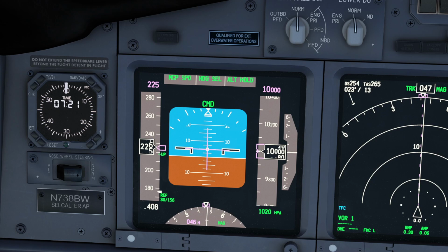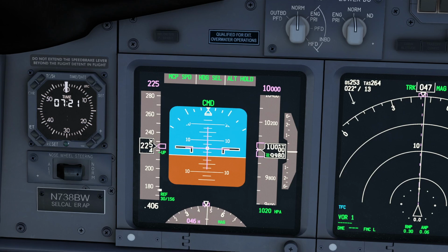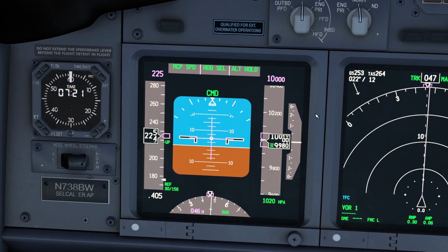The second one is that you must be in a balanced condition. I will use the word balanced because actually the manual says that you must be in trim, okay? So you must be in a trim condition, but like the flight director, it doesn't need to be 100%, but at least you need to be in a balanced position. So pretty much you have to release your yoke and then engage the autopilot.